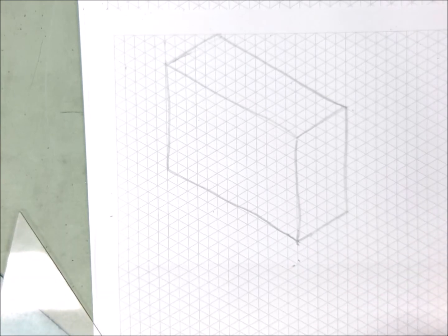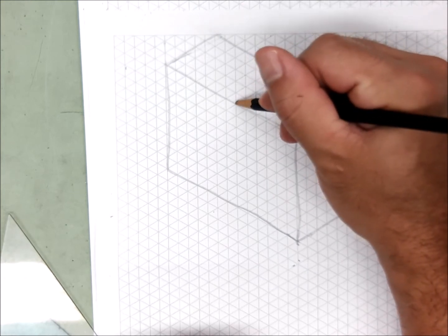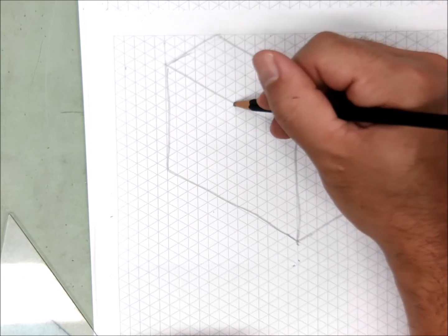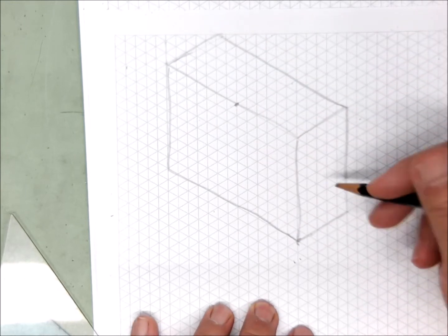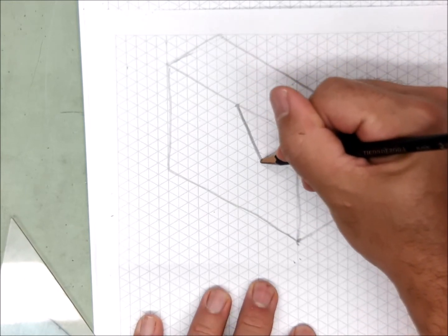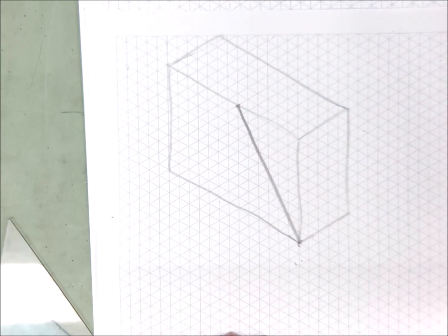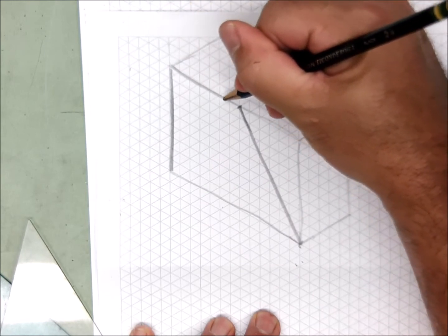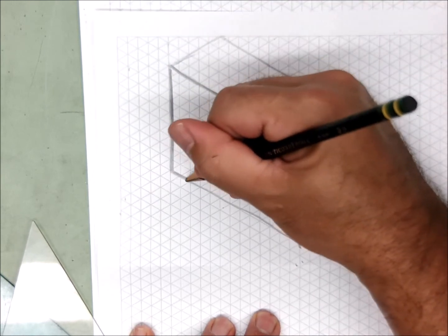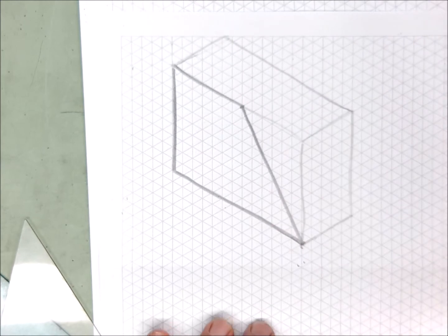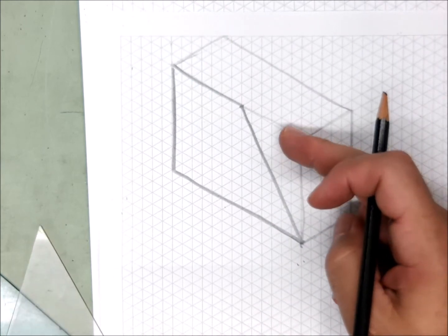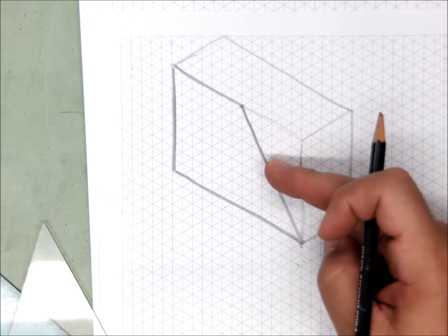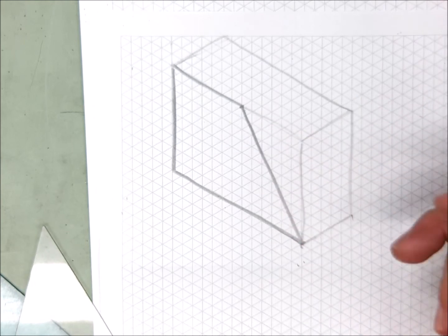If I look at my sample I'm working off of, my slope starts somewhere around here on the front, right? And then it ends down here on the bottom. So, where do you start? Where do you stop? And that's it. You need this distance from here to here, and this distance from here to here. And then the rest is gravy. I have no idea what the angle is. Doesn't matter. It will not measure correctly in isometric because it is a non-isometric line.